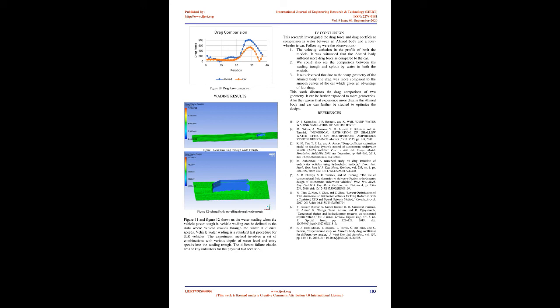The number of elements and nodes present in the Ahmed body are 315,954 and 57,314 respectively. We also checked the orthogonal mesh matrix quality statistics and it was found to be good, and can be seen from Figure 6 and Figure 7. It can be seen that most of the elements have an index that lies between 0.7 to 1, which is expected from the orthogonal index.